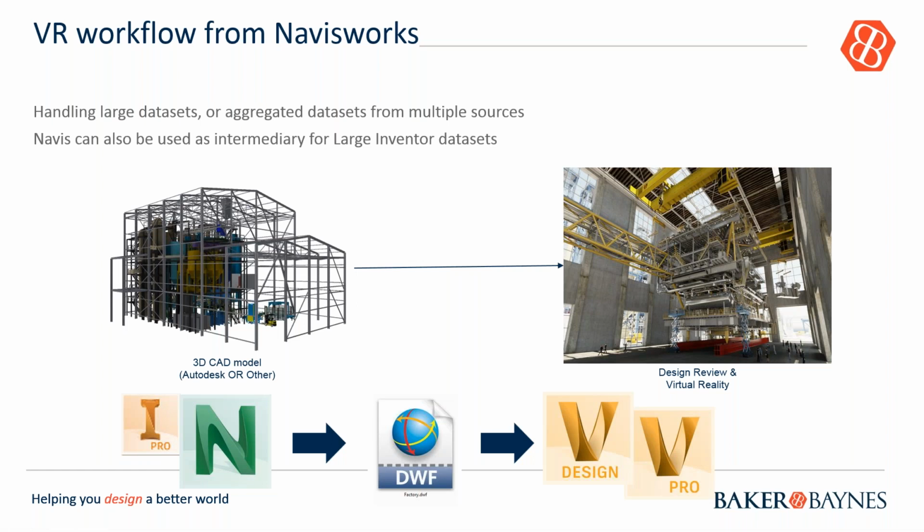Having data coming in from multiple sources can be handled very well in Navisworks. The workflow will be having the 3D CAD model done, either using Inventor or other CAD applications, taking that into a Navisworks environment. You could export that out to a FBX file, a DWF file, and then send that directly into VRED for virtual reality design review.